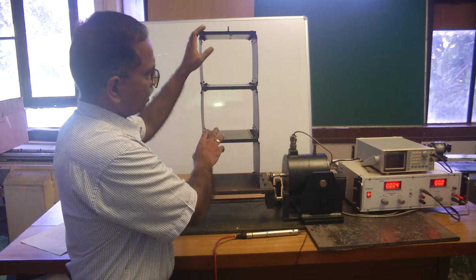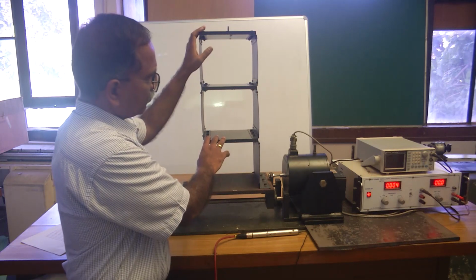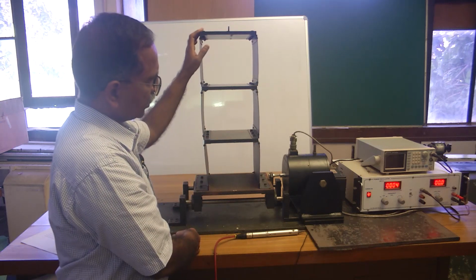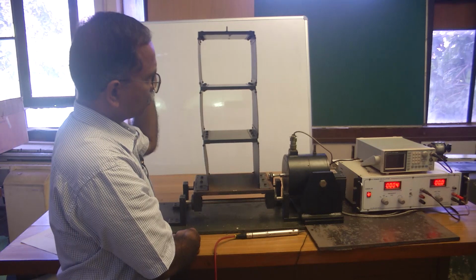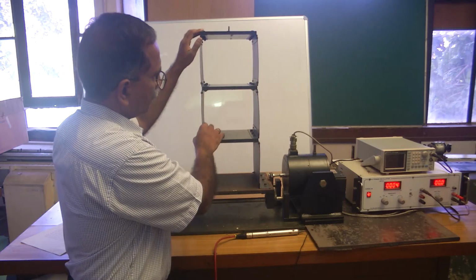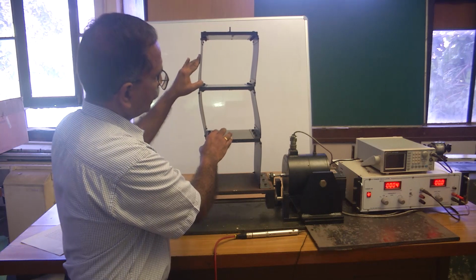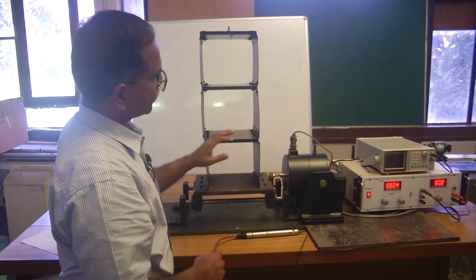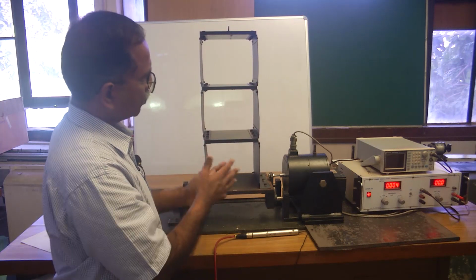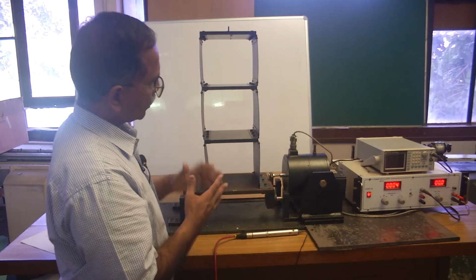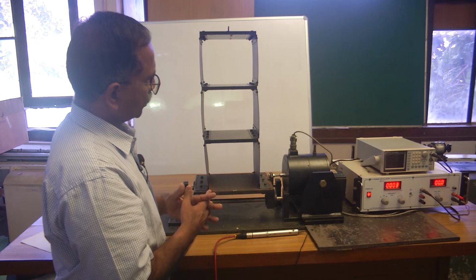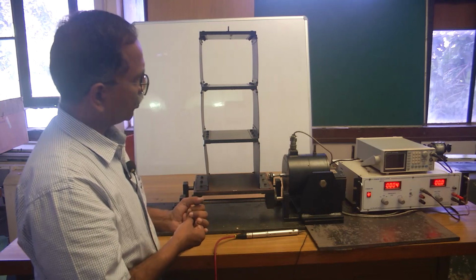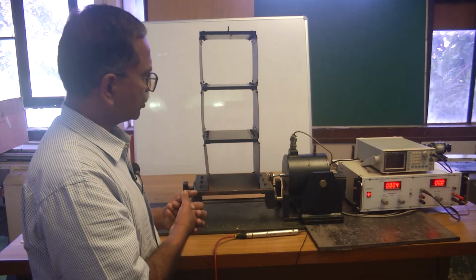Now, as I said, it's relatively tough to excite all the subsequent modes. Maybe the first mode might be easier to excite, so you can see that this is the first mode that got excited. Getting the second mode or third mode is going to be relatively difficult, because we have to pull and push all these masses in exact proportion corresponding to the second or third mode shape, and then release it, which is slightly difficult to initiate at t equal to 0, and therefore higher mode shapes are hard to obtain by giving initial displacement conditions.